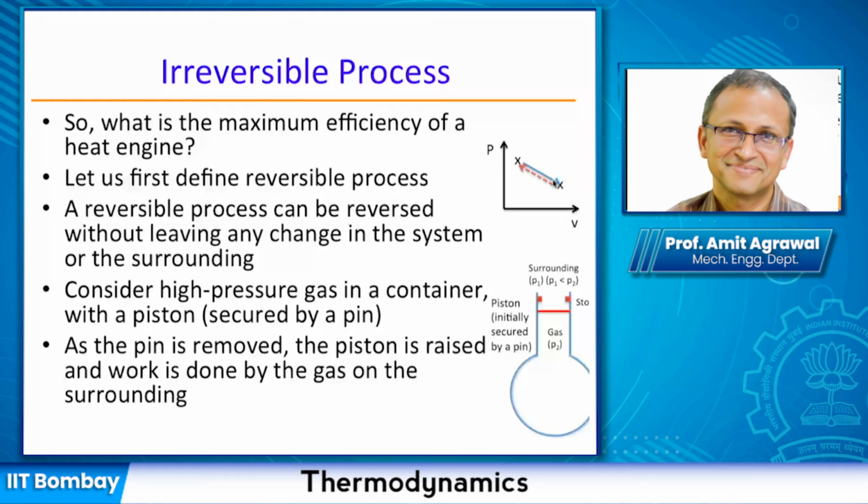So does it mean that for defining reversible, we don't care about these intermediate points? If I'm going from one state to other, I must be able to come back, right? Yes, and unless you can define the state in between, you cannot come back. So we are saying the opposite to what you are thinking. Unless you know all the states in between, you are not going to get a reversible process. The reversible process will only happen if you know all the states in between, and of course you can reverse the states altogether when you take the reverse path.